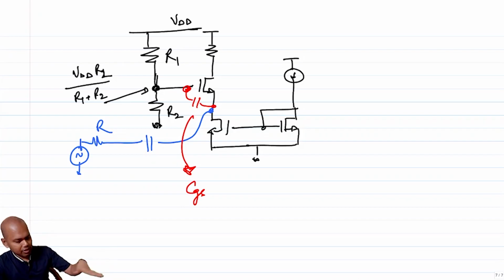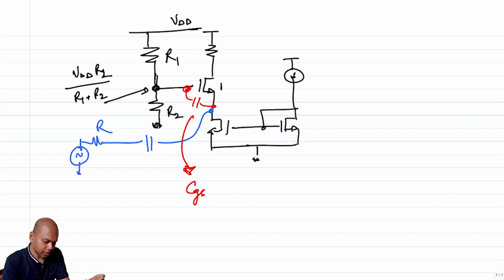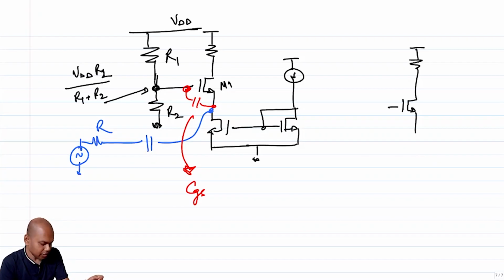Having many things on the paper might be clumsy. So what I'll try to do is reduce the circuit to a manageable proportion, and I'll only concentrate on what is happening around M1 in the incremental sense. So let's concentrate on whatever is happening at M1. I understand that I have a current source on the bottom, so incrementally that is not required, and I have an incremental current of Vi by 2R that is flowing in.